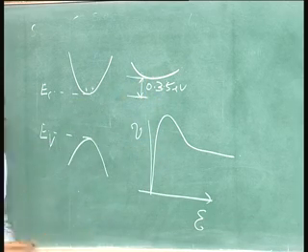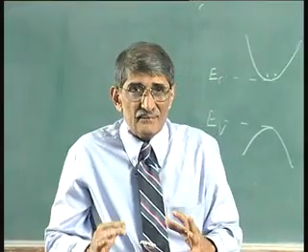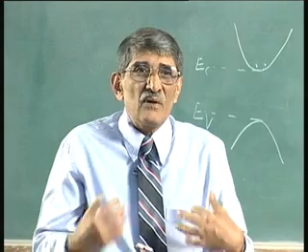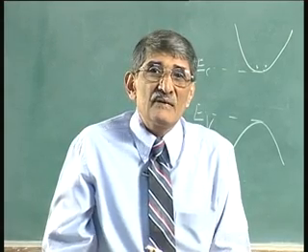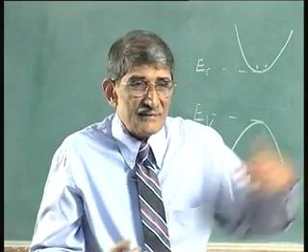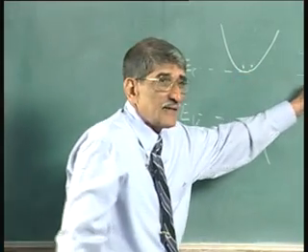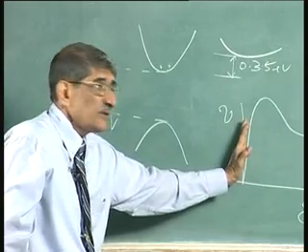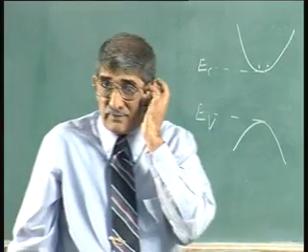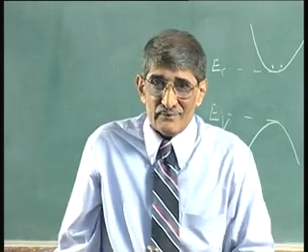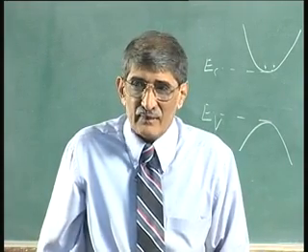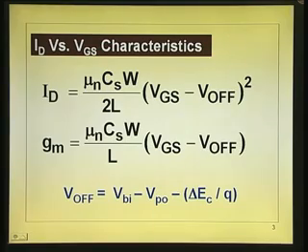Your velocity can be much higher, and you do not have that transfer. So, what happens is the electrons reside in the lower valley, and the entire transport takes place in the lower valley itself. Virtually people talk of the transport of electrons without intervalley scattering. So, one scattering phenomenon is cut down. So, it is a very high mobility right through all the way. V will be mu into E, that is all. That will be the type of velocity. So, you can get very high velocities in the short region.